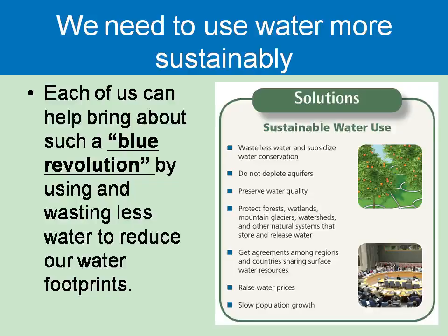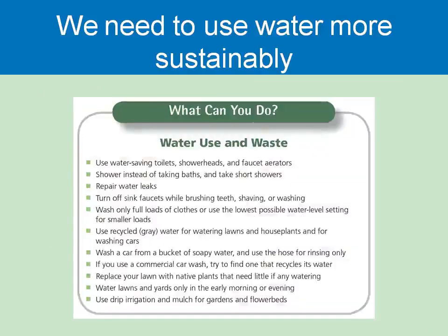Another one is removal of pollutants. The various physicochemical techniques used for removal of chemical, biological, and radiobiological pollutants include adsorption, electrodialysis, ion exchange, and reverse osmosis. Of the various techniques, reverse osmosis is based on the removal of salts and other substances from water by forcing the latter through a semi-permeable membrane under pressure that exceeds the osmotic pressure, so that flow is in a reverse direction to the normal osmotic flow.